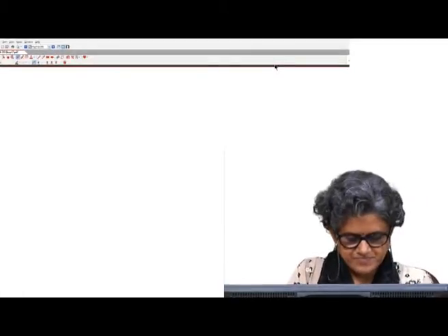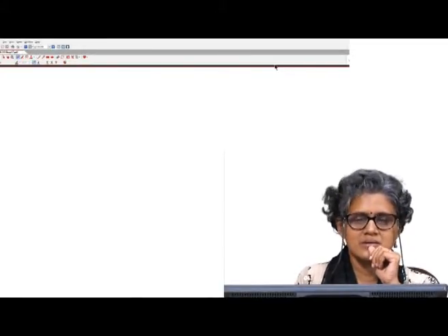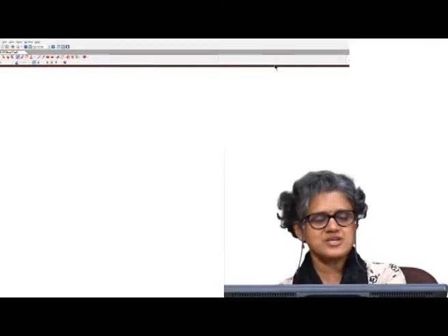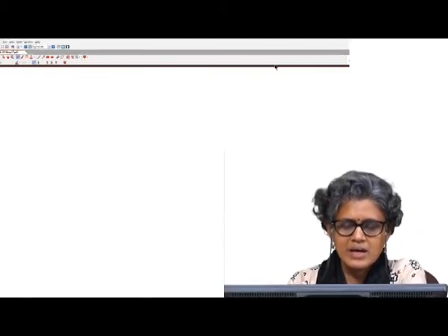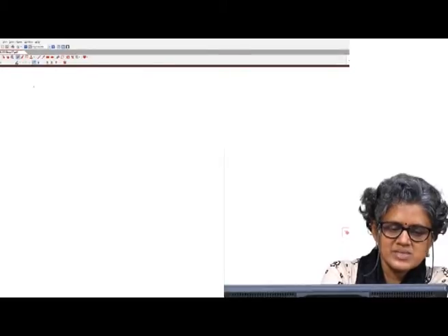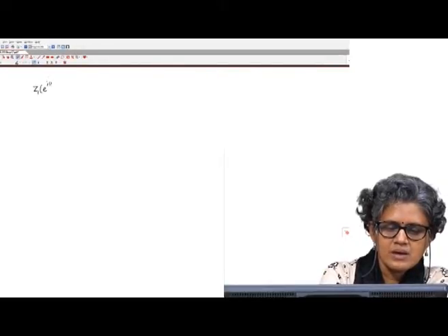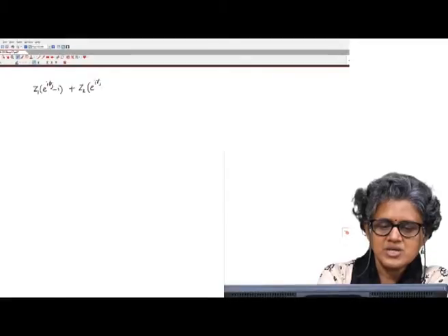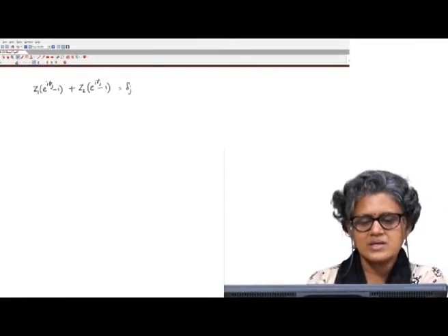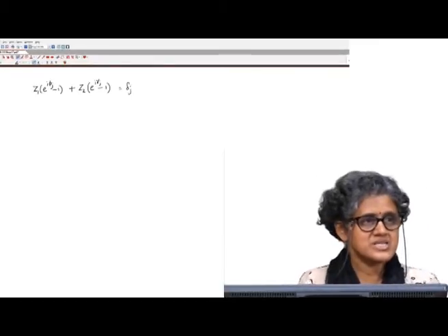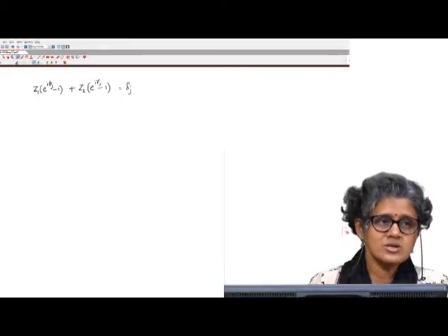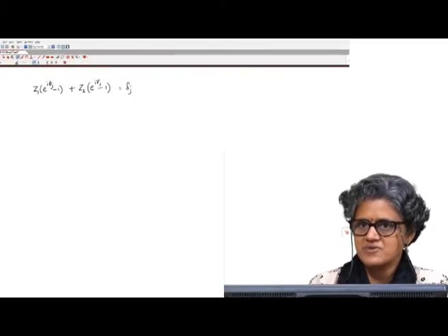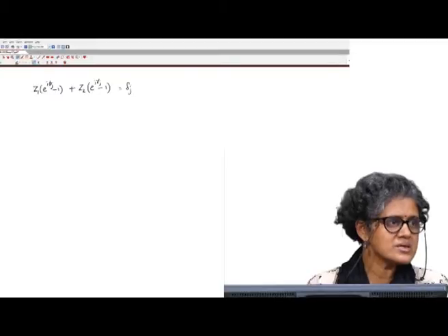So, we have looked at the dyad method of synthesis for motion, path and function generation. And we started off with this equation, basically Z1 e power I phi j minus 1 plus Z2 e power I gamma j minus 1 equal to delta j, where if delta j and gamma j are specified, then you have your motion generation problem, or if delta j and phi j are specified, then you have your path generation with prescribed timing.